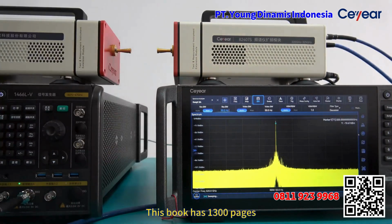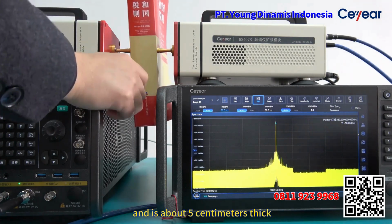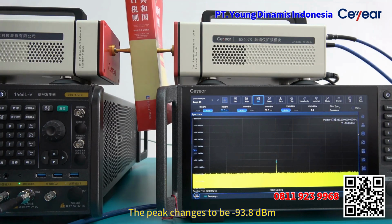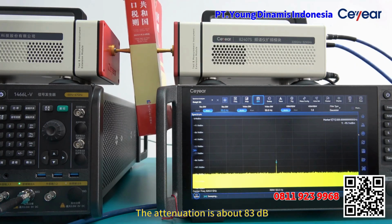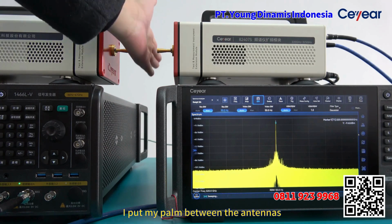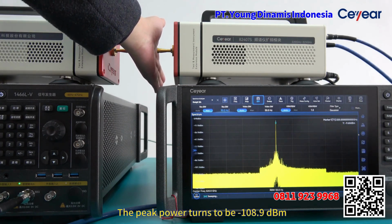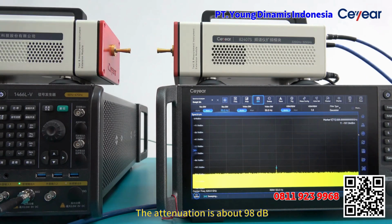This book has 1,300 pages and is about 5 centimeters thick. The peak changes to minus 93.8 dBm. The attenuation is about 83 dB. I put my palm between the antennas. The peak power turns to be minus 108.9 dBm. The attenuation is about 98 dB.